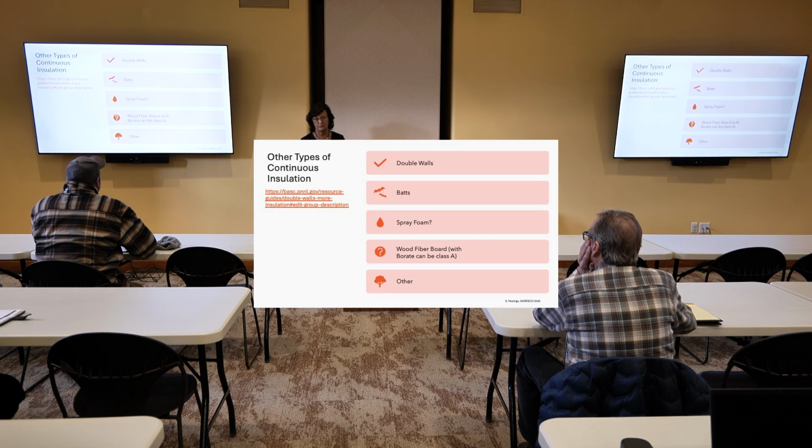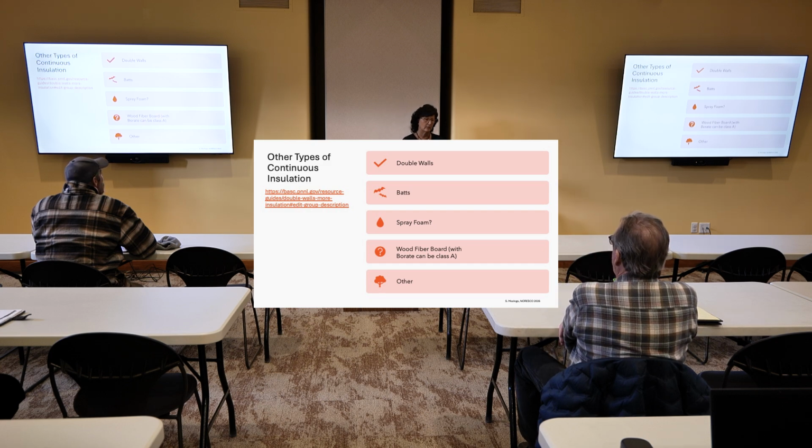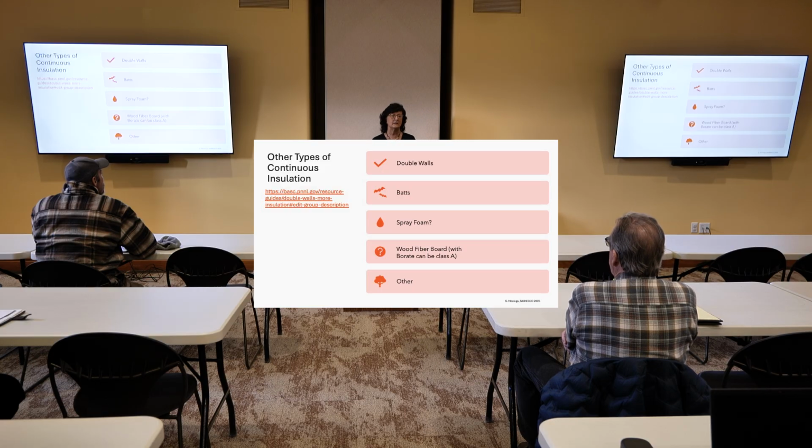There's all kinds of great ways. If you just Google any kind of double wall, the National Association of Home Builders has great videos on double walls. There's all kinds of information on double walls. Not everybody likes it because a double wall takes, we start encroaching into our square footage, right? And so not everybody likes it, but there's ways to keep it down. Instead of, you might have a 2x6 wall and then a small wall just for your plumbing inside. It doesn't get too bad.